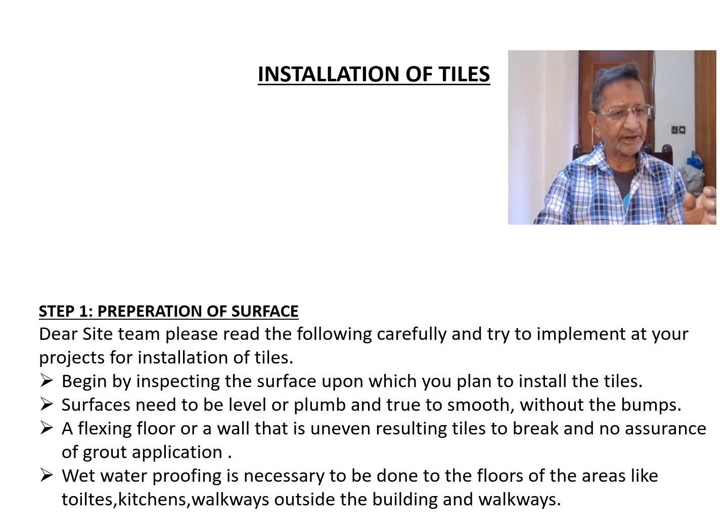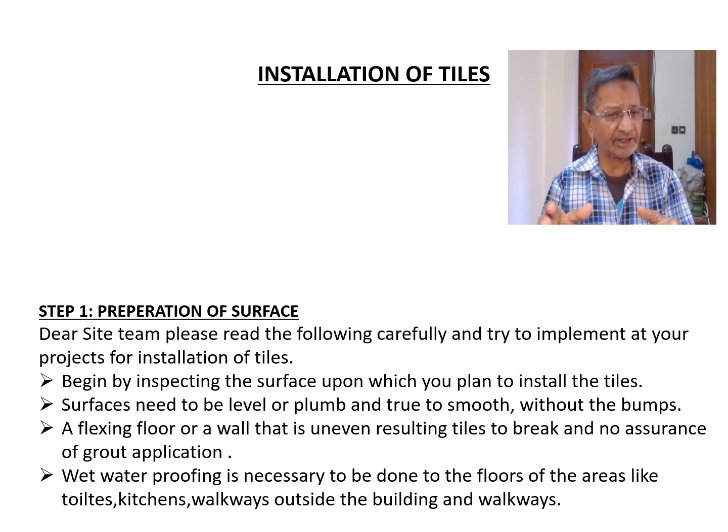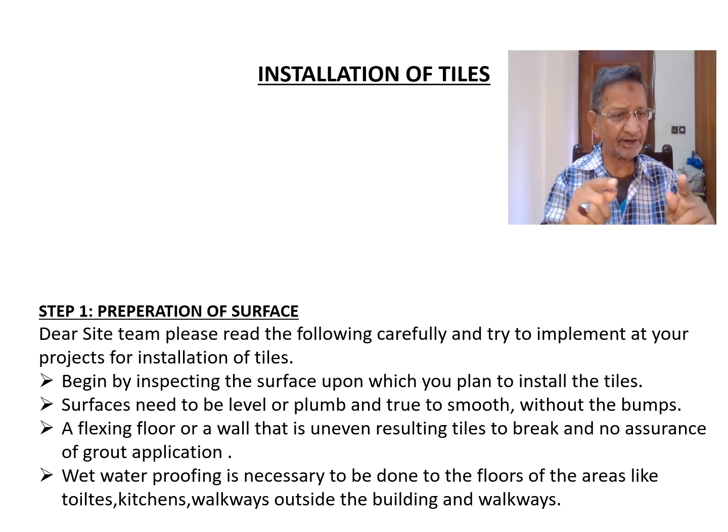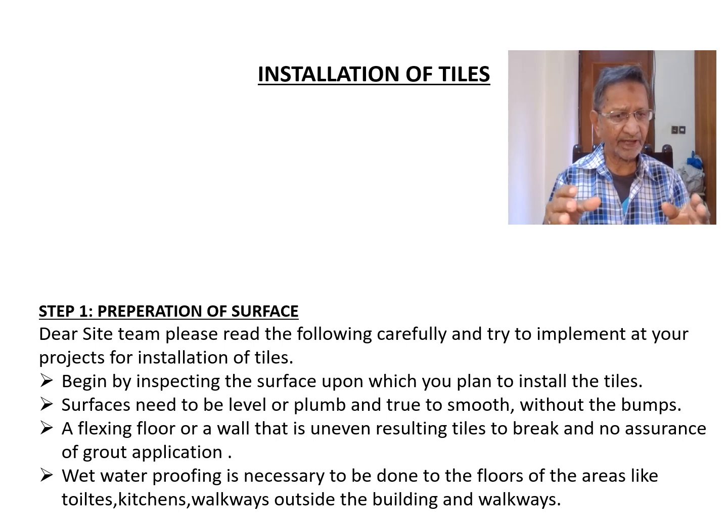It is critical that the surface is leveled and smooth, and free of bumps. If it is an uneven area, this will result in improper fixing of tiles. A surface that is not even can lead to problems such as tile breakage, uneven grout application, and it also results in problems with the floors.